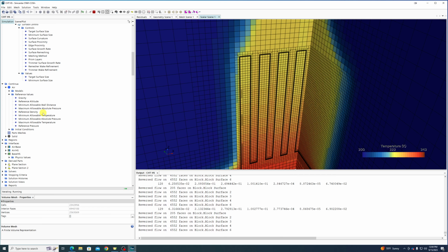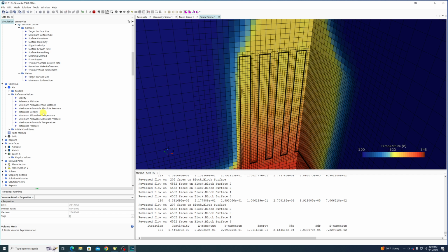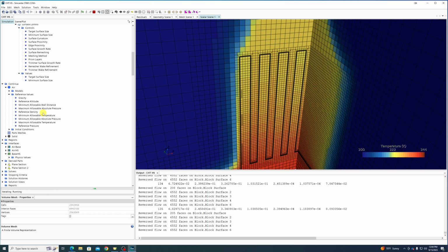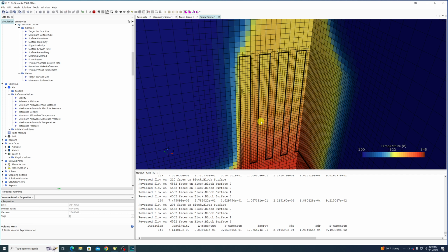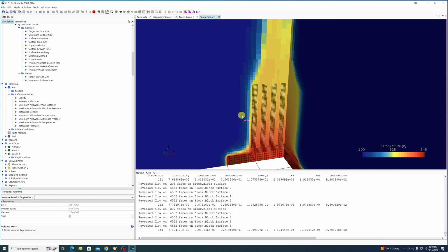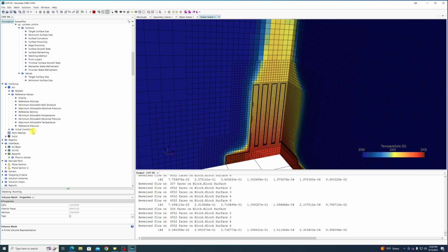The things you want to measure, perhaps, that you wouldn't think of before. You might have thought of measuring temperature before, but you also want to measure things like heat transfer coefficient. What is the maximum and minimum internal temperature? You want to look at what is the temperature of the solid in space. What does the temperature field inside of the solid look like? And things like that. And as an example here, let me just pull up